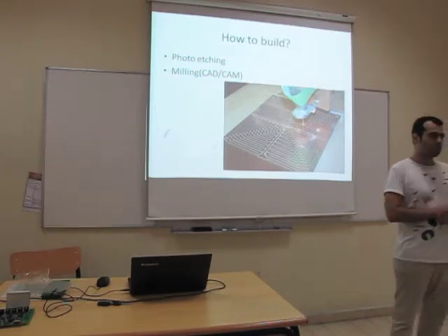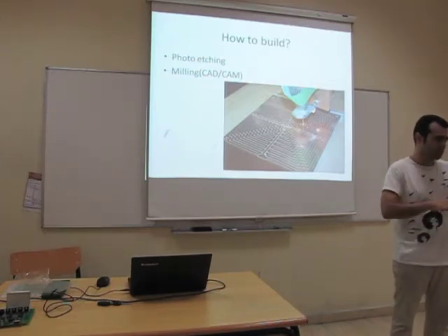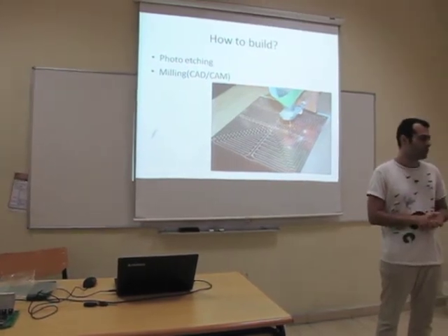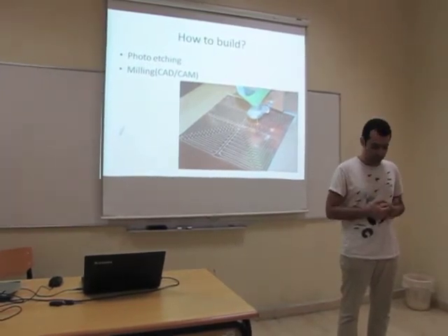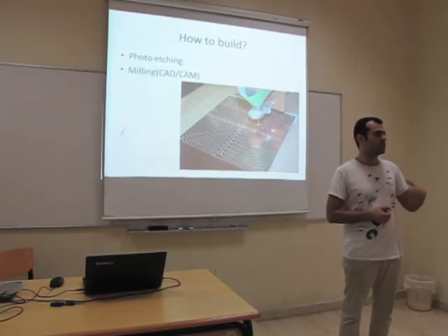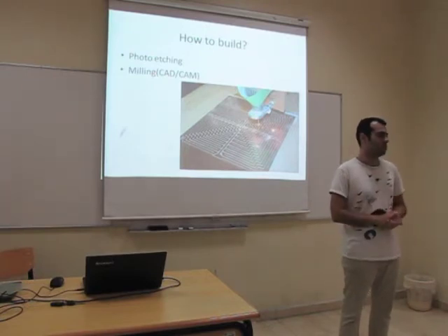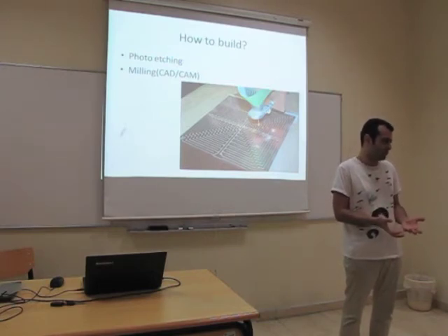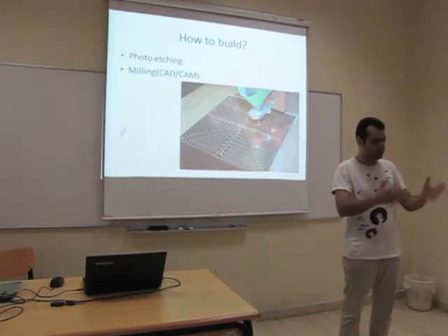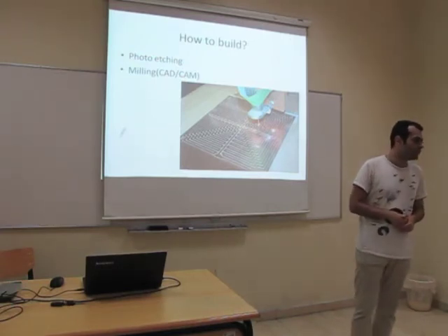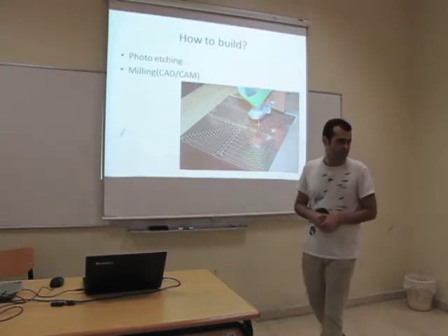They laminate it with some photosensitive material, then they put these films on it, then they project some light on it, mostly UV. Then with some solvents, they dissolve the parts that were not exposed to light. Then they put the whole thing in acid. The places that have no protection will dissolve in the acidic solution, and the other parts which you see on the films will remain. This is how it works.